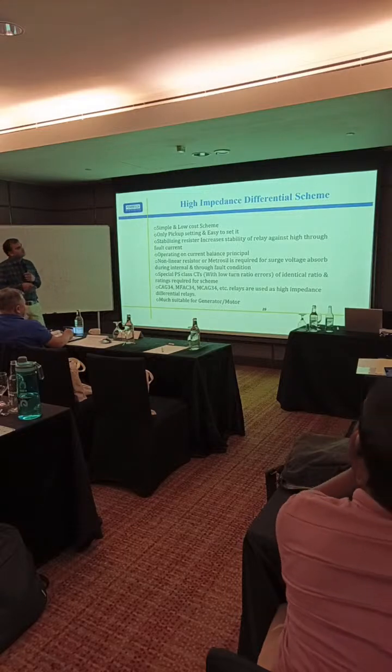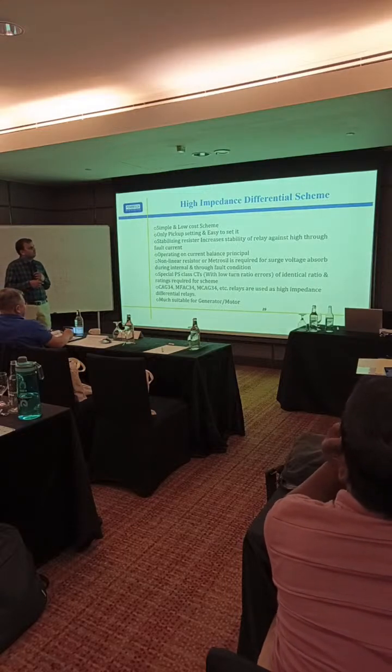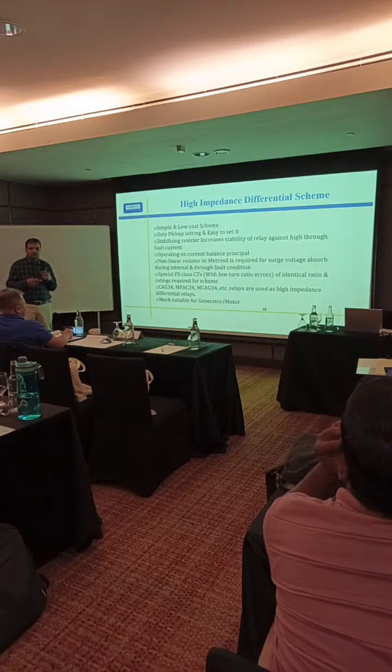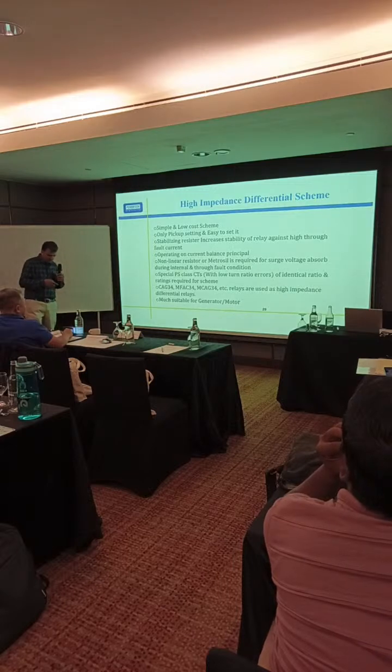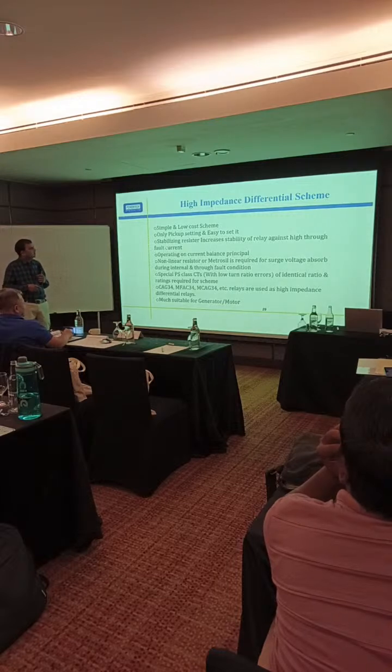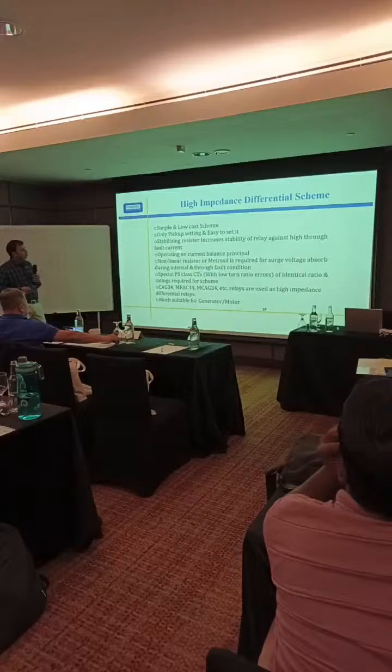Then this protection was predominantly used in many places because it is easy to set and understand. So the stabilizing resistor and everything you learned yesterday, how to calculate that resistance,